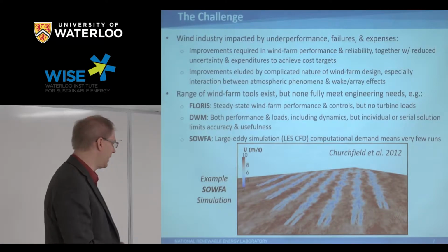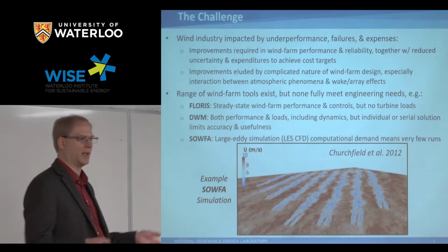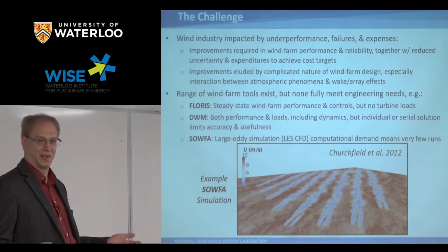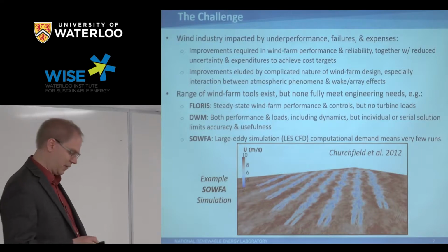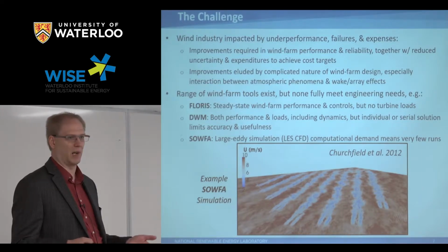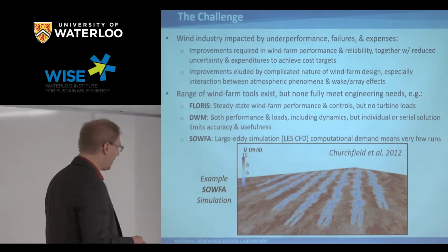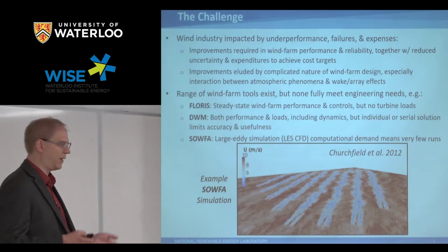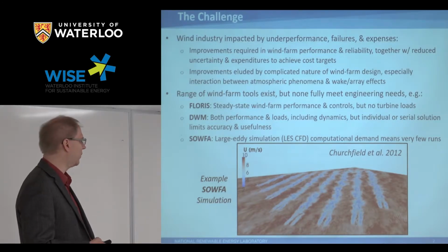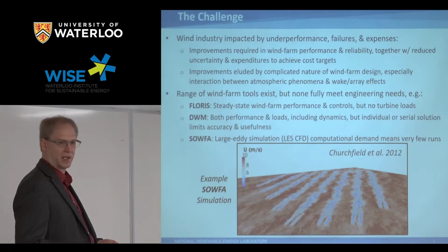A simulation like this, where you're analyzing basically all the turbines in the wind farm, probably takes a couple weeks to run. So while you can learn a great deal of insight about what's going on in the flow, you're not going to do that in a design loop process where you're trying to optimize the turbines. And then in the middle, and that's where I focus my effort, is on what we call engineering fidelity tools, things that can run very quickly, but capture the main physics we need to actually do design work.